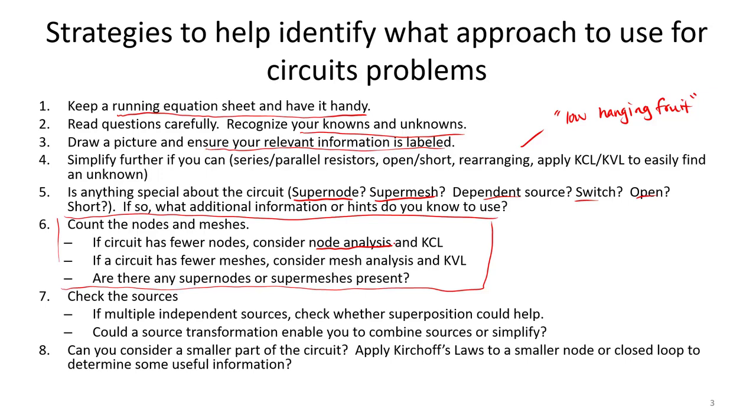Similarly, if your circuit has fewer meshes or fewer closed loops for current to flow, consider mesh analysis. Maybe instead of having to write equations for several nodes, you could just write one Kirchhoff's voltage law equation for your mesh. So keep that in mind. And also watch out for those supernodes and supermeshes. Those can also help simplify questions considerably.